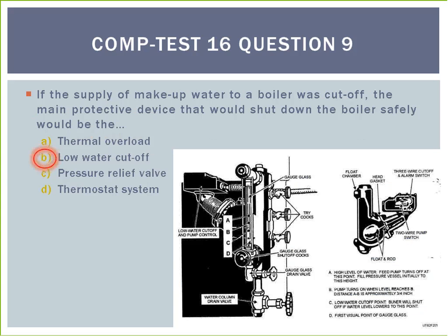Boilers are equipped with low water cutoffs as a safety feature to shut down the boiler in the event makeup water is lost. Answers A, C, and D all have to do with temperature or pressure safeties and do not pertain to water level.